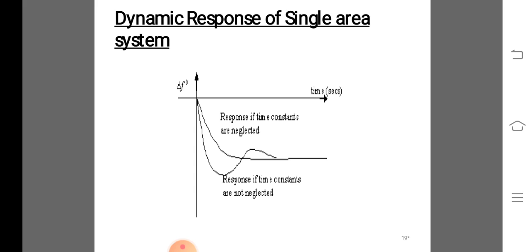Even though it is a little bit involved, for simplicity assume that the two areas are equal, and neglect the governor and turbine dynamics, which means that the dynamics of the system under study are much slower than the fast acting turbine governor system in a relative sense.